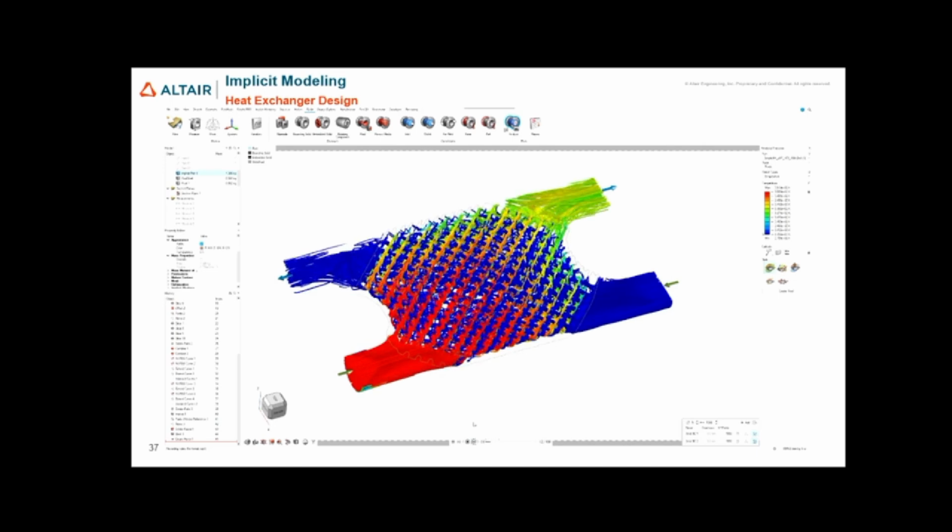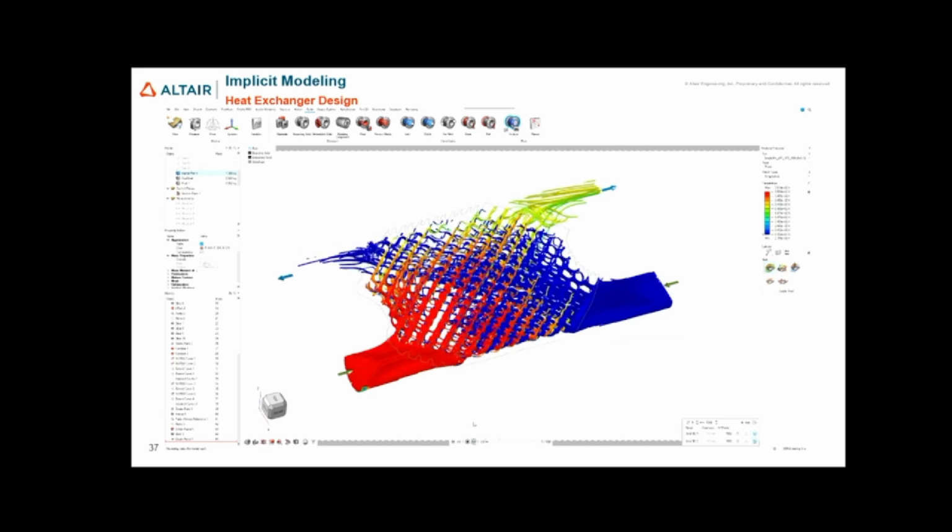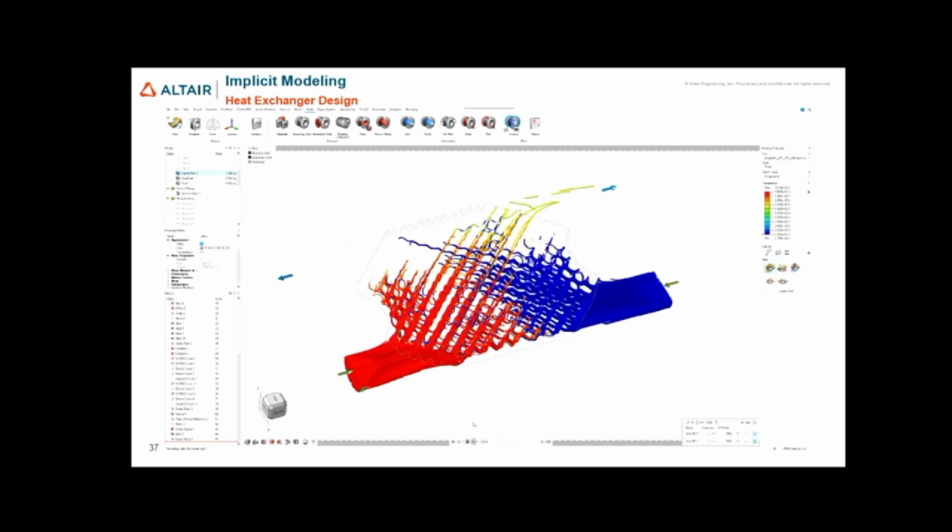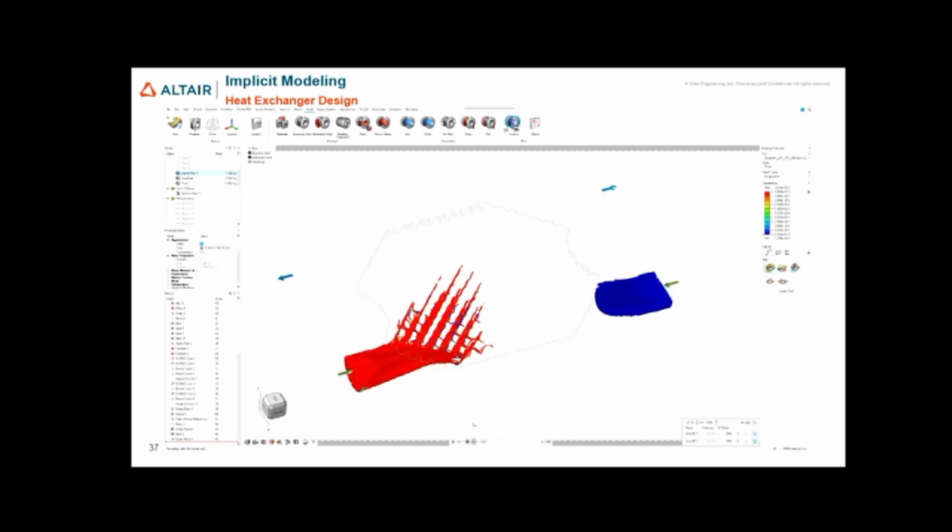And the solver is going to do the hard work of splitting those fluid domains. You don't need to do any meshing. It's basically just going to figure out from the inlets to the outlets with the different materials how it actually creates the fluid domain of each material. And it's done on the GPU. It basically runs in seconds, if not minutes, depending on the resolution that you're running.